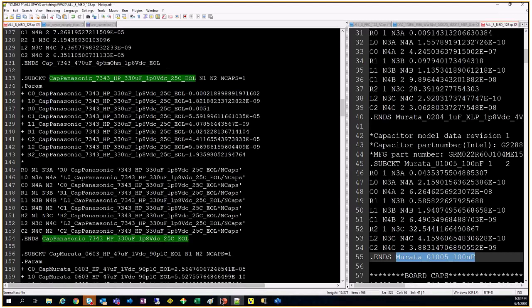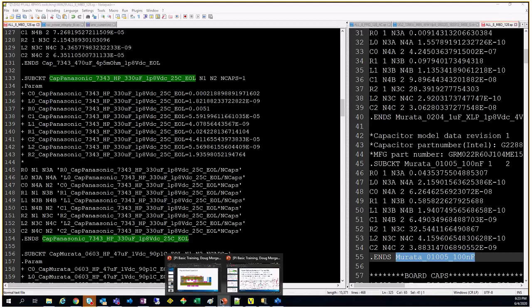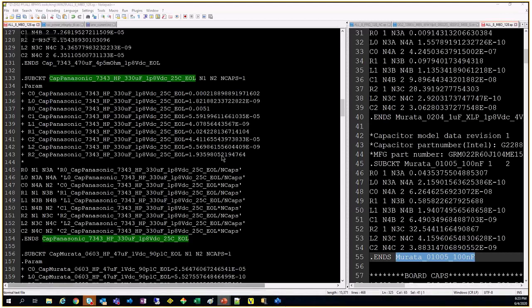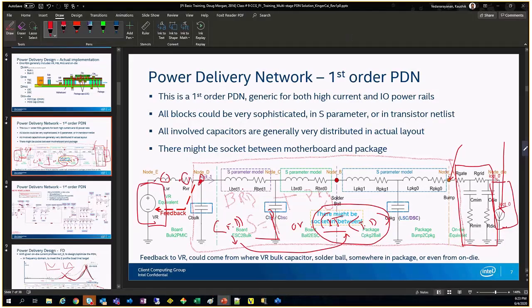Whenever you want to build a SPICE deck, immediately start drawing the subcircuit. You see the PPT. Draw an RLC network on paper. This is my VRM, this is my RVR. This block is going to be my S parameter. This is where I'm going to hook up. If someone gives you a SPICE deck, you trace it like that: this node is connected to this node, at this port is hooked up this capacitor. If you build this subcircuit, you will immediately understand what is built.